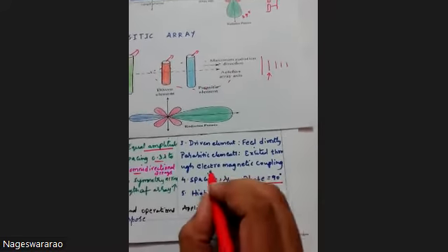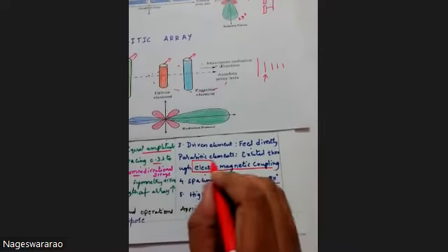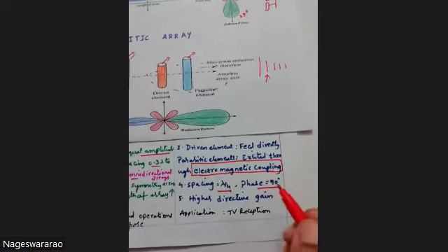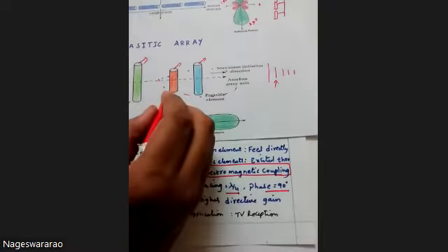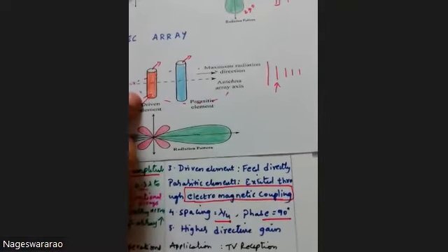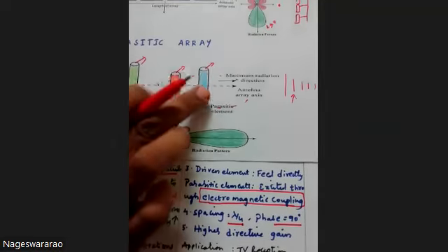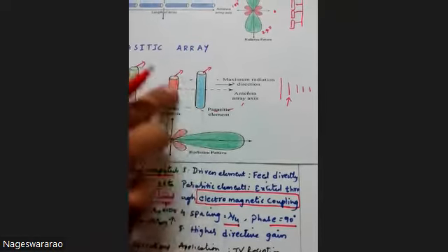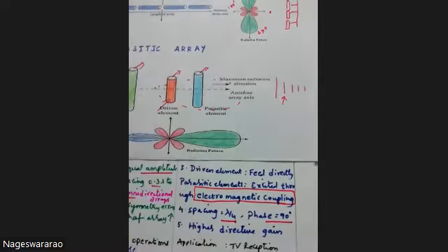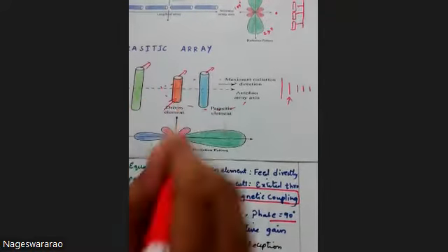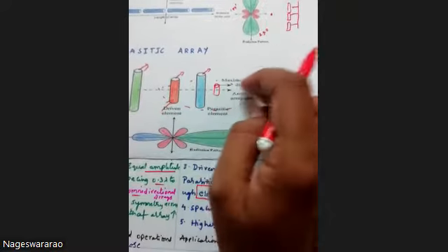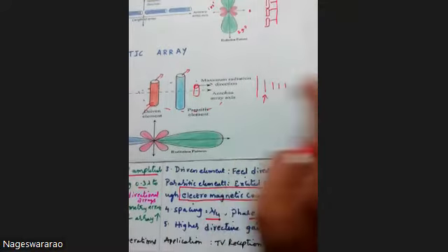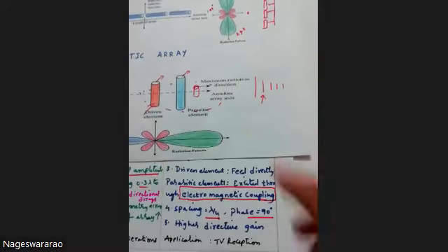And here the main concept is electromagnetic coupling. You can clearly understand this in Yagi-Uda antennas. Electromagnetic coupling means nothing but that the driven element is provided feed directly. With the effect of this driven element, because of the coupling between these two elements, the parasitic element also starts providing the electromagnetic field. With the effect of this element, the next element also gets excited. In that way, so many elements get excited in a continuous way. The fields of all the elements get added and you get a radiation pattern like this.